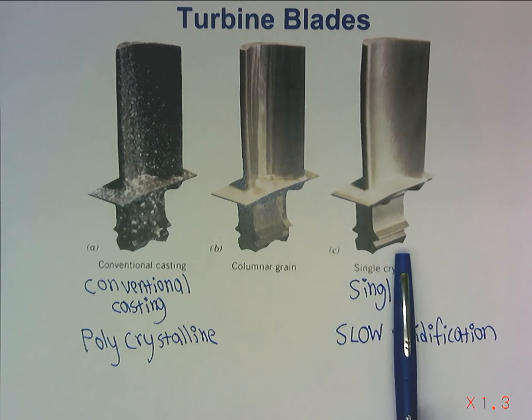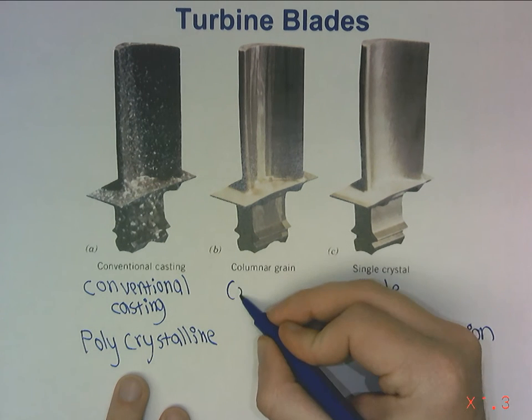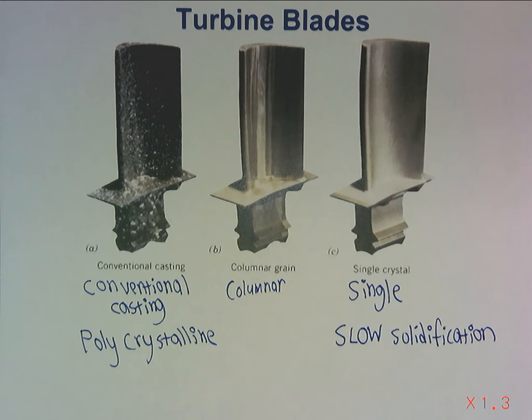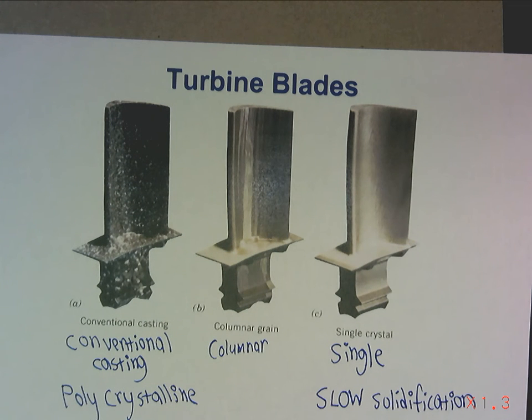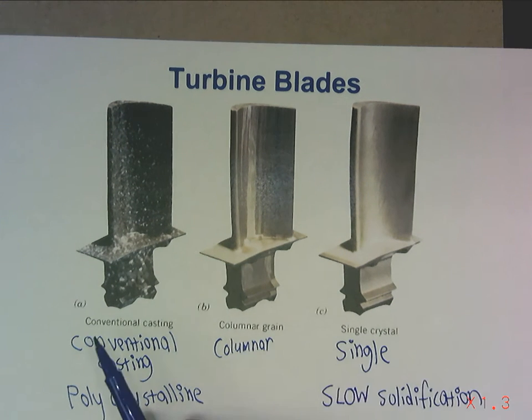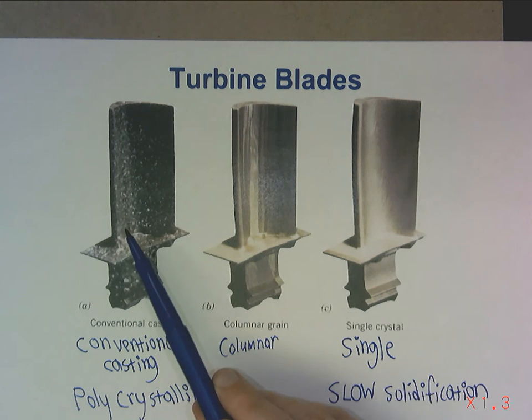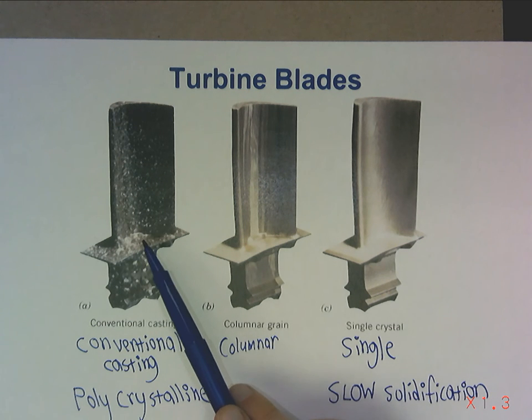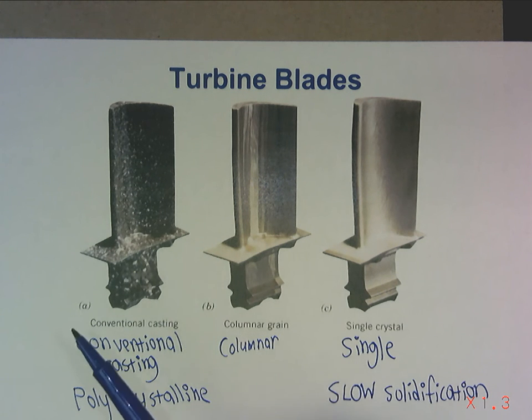As an intermediate, we've got this guy hanging out in the middle, which is columnar grains. If you're able to look at the picture, the part has been treated with an acid on the surface to bring out the grain boundaries. Actually, over here, we can see all these different spots that are different shades of blue and gray. And each of those little blue and gray spots in here is its own grain, which are actually very large grains because we're not using a microscope.